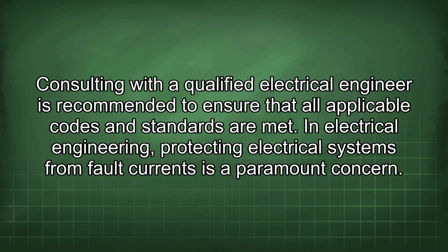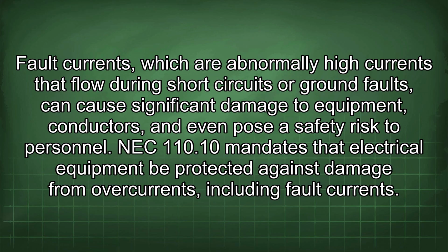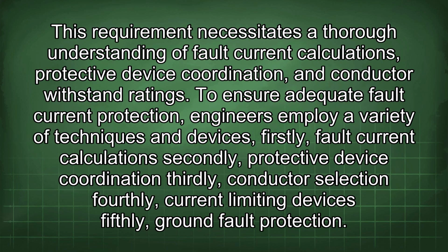In electrical engineering, protecting electrical systems from fault currents is a paramount concern. Fault currents, which are abnormally high currents that flow during short circuits or ground faults, can cause significant damage to equipment, conductors, and even pose a safety risk to personnel. NEC 110.10 mandates that electrical equipment be protected against damage from overcurrents, including fault currents. This requirement necessitates a thorough understanding of fault current calculations, protective device coordination, and conductor withstand ratings.